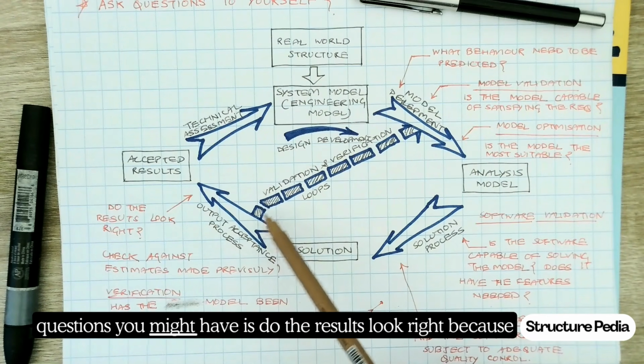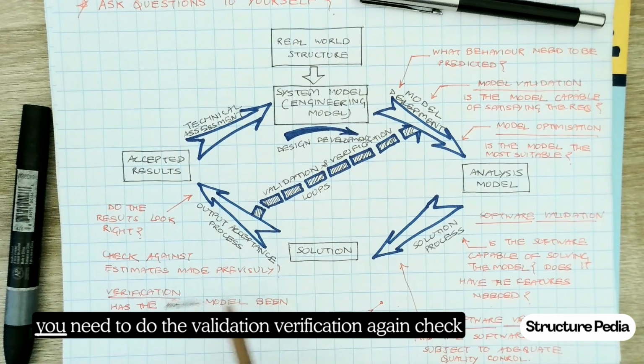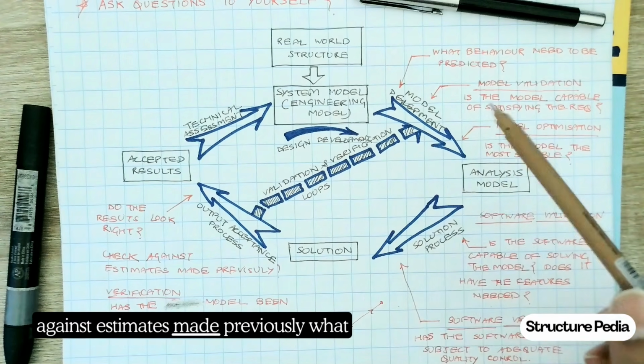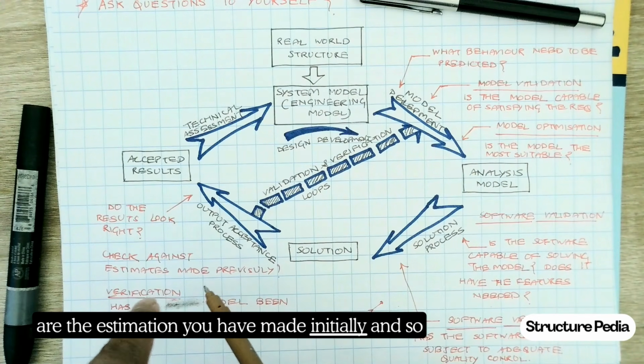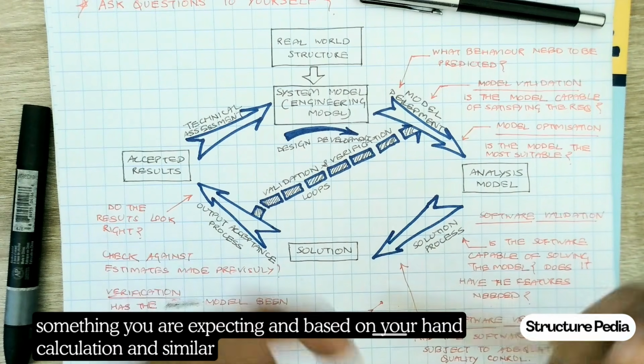The other question you might have is, do the results look right? Because if they look right, only then can you accept those results. Otherwise, you need to do the validation and verification again. Check against estimates made previously. What estimates did you make initially, what are you expecting based on your hand calculation?